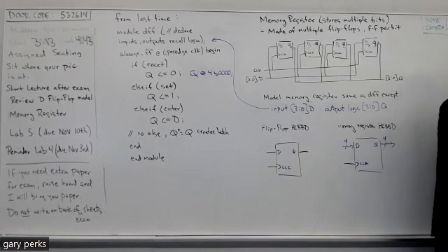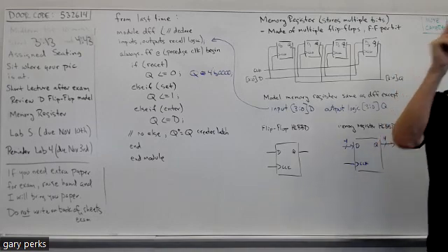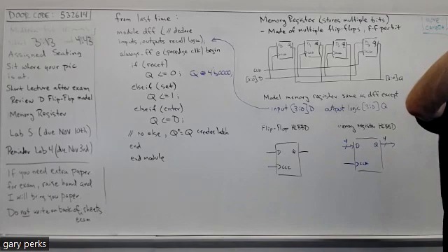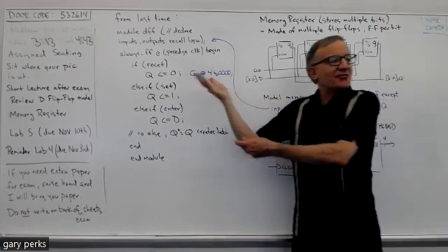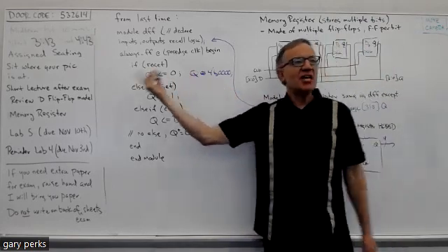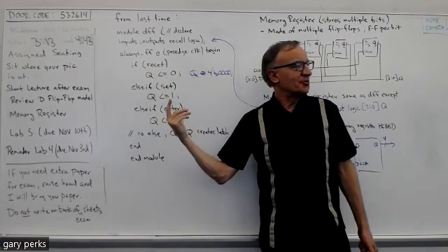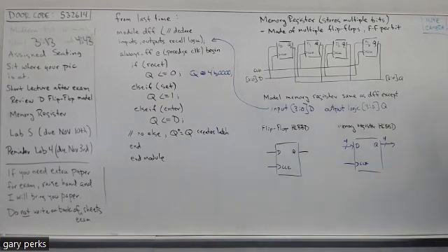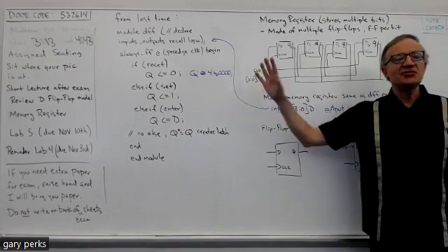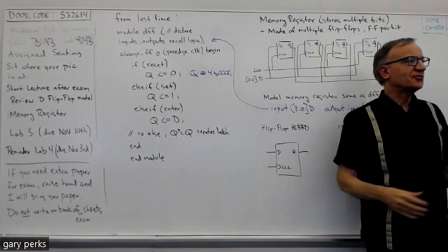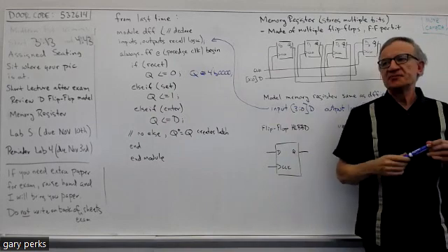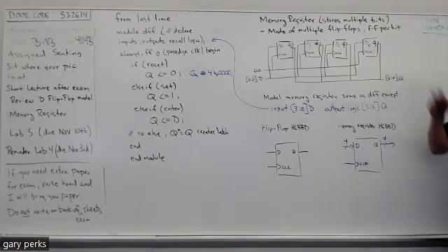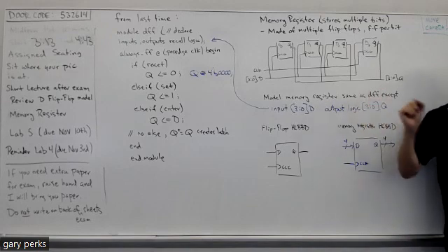See, we could have had you do this for the RCA when it was made up of all full adders. You could have just taken the full adder code and just made the inputs multiple bits and the output multiple bits. And the software wouldn't have made the RCA for you. It would have made those connections that you did essentially manually in the top module. Okay, but we didn't tell you that at this time because we wanted you to get practice with doing structural modeling. Okay, but for Lab 5, this is the way we want you to approach the register.